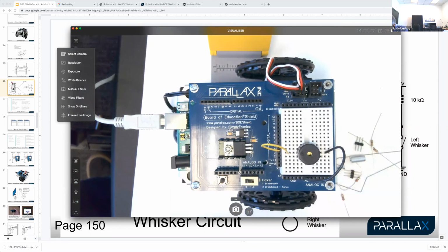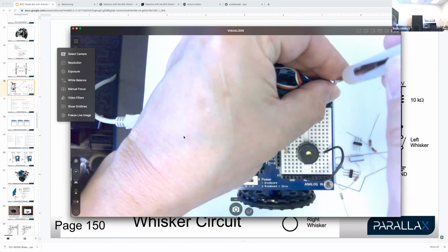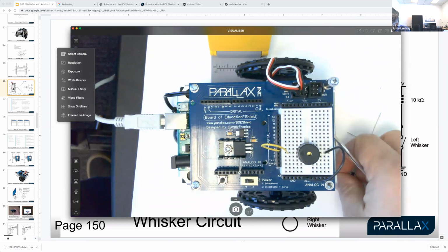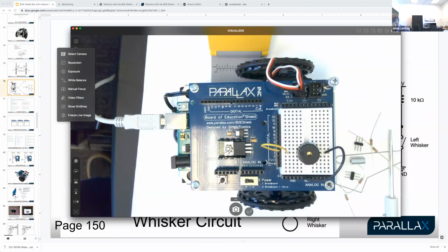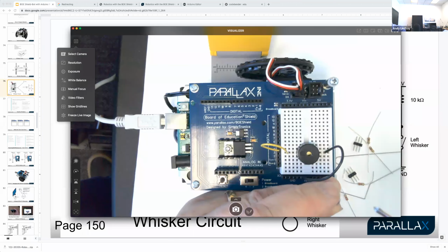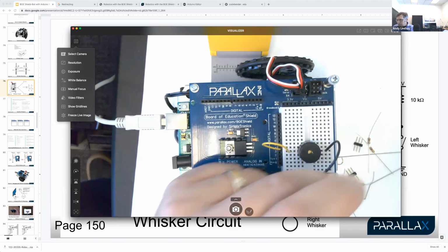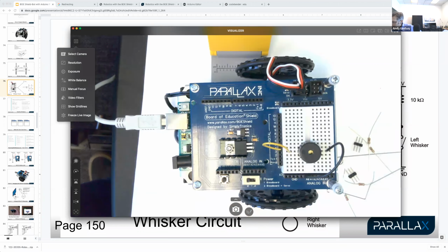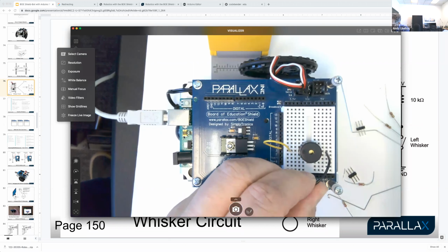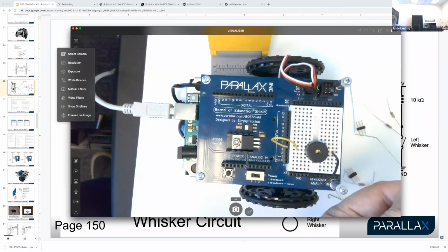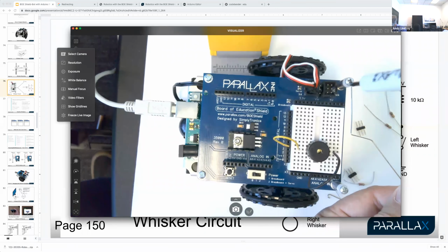So I usually start the screws and get them partway screwed in. Put the nylon washer on the screw, then put the standoff on the screw, then get it started in one of the corner holes by the breadboard after removing the original screw, but don't tighten them down all the way. So then what you can do is take that whisker and, I'll put the left one above the washer, and I'm just going to hook it in there so that it's hanging on to the shaft of the screw. Then I'll tighten it down.